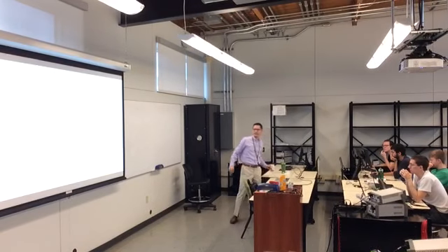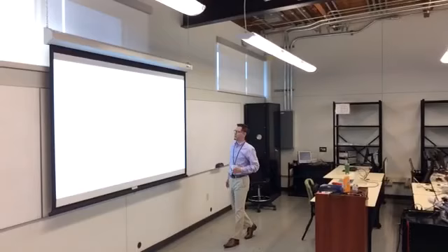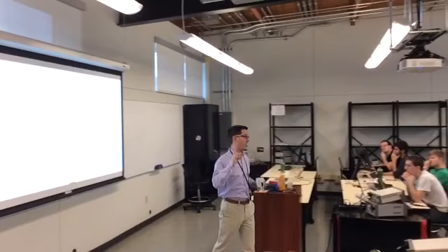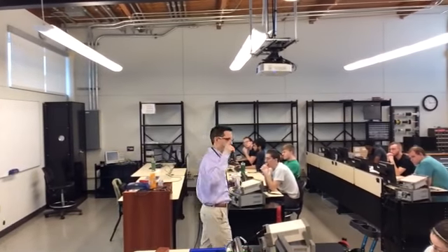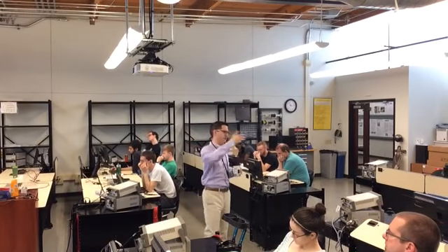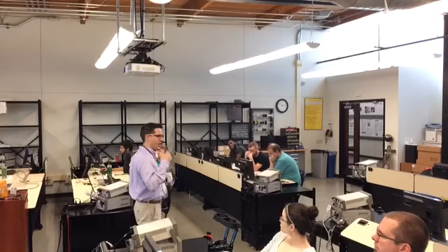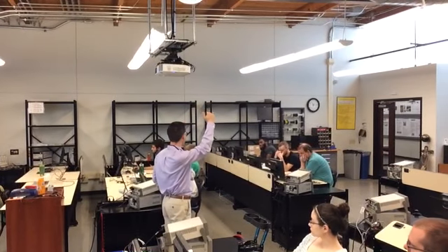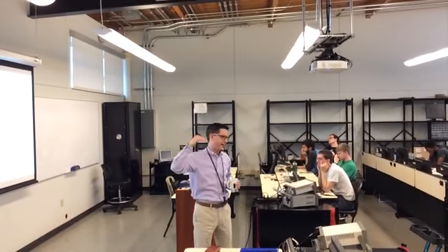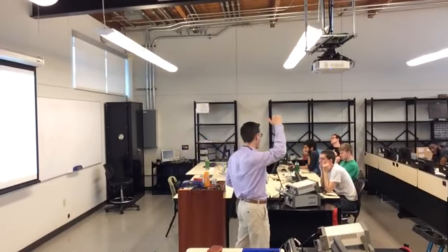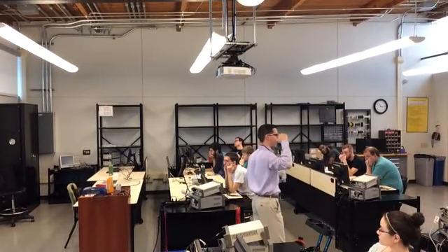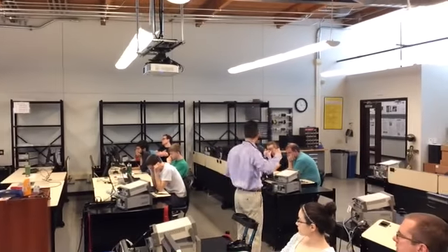Basic modes, as I mentioned, and let's be particular about these keywords. In the up mode, the timer starts at 0 and goes up. Once it surpasses the maximum value that's in top, it causes an overflow event. So remember, when a counter or a timer goes up, up, up, up, up, and then exceeds the maximum value, it causes overflow. Down is the opposite of that. It starts at the top value and counts down, down, down, down, down till 0, and then it underflows. So overflow means I've gone too high and I wrap back around. Underflow means I've gone too low and I wrap back around to the top.